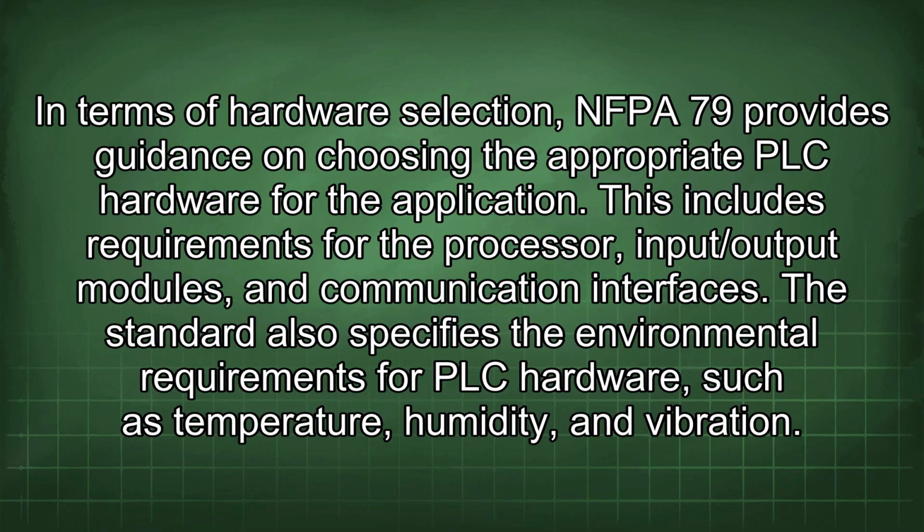In terms of hardware selection, NFPA 79 provides guidance on choosing the appropriate PLC hardware for the application. This includes requirements for the processor, input/output modules, and communication interfaces. The standard also specifies the environmental requirements for PLC hardware, such as temperature, humidity, and vibration.